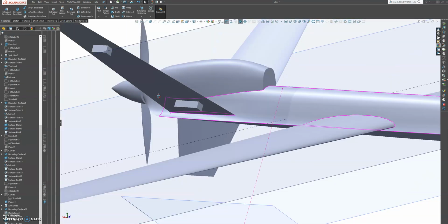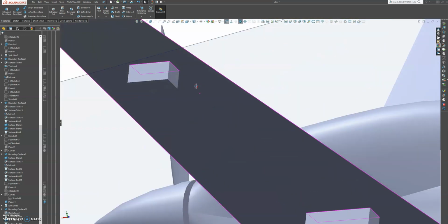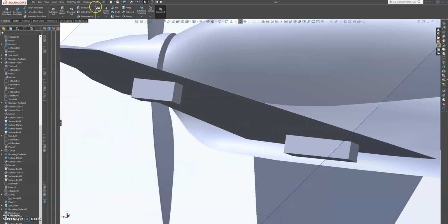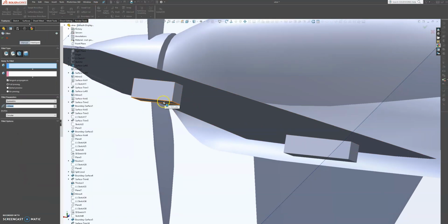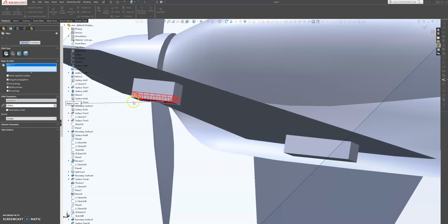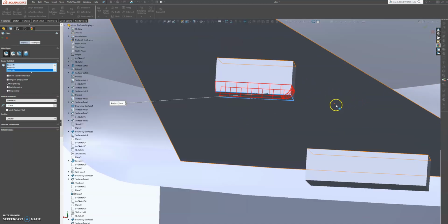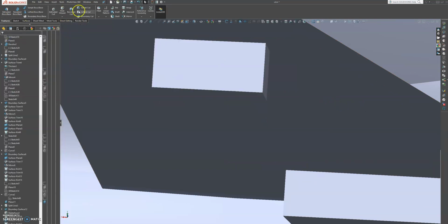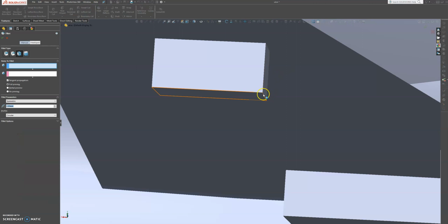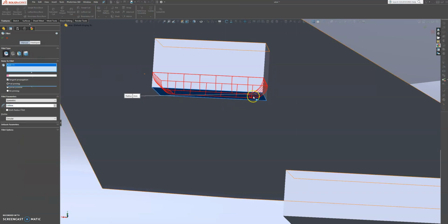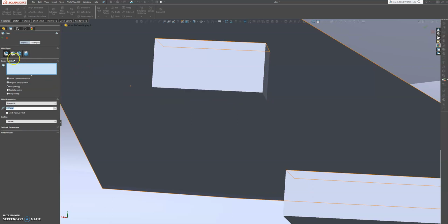That's good. Okay, now we just have to come in here and let's add some fillets. Let's see, quarter fillets we want. Now we don't need to fillet all that much, just this side, this side, this side. Or we can just go to fillets and add our fillets first to just this edge here. Clear selections. Okay, just add to this edge.